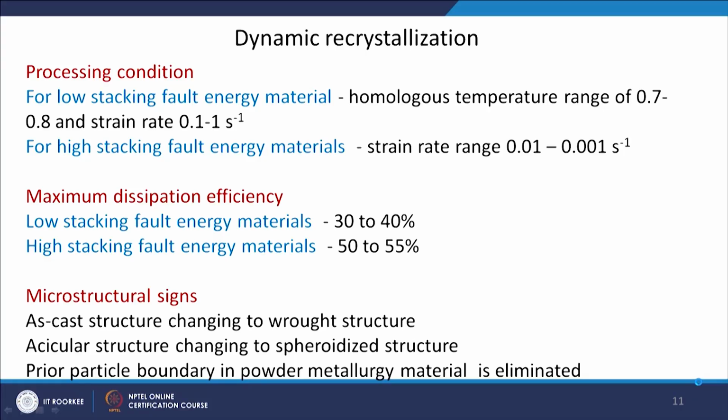So, wherever you have high efficiency, 2-3 samples from there, then maybe a couple of samples from the unstable region to identify whether in these regions some defect is occurring. Okay. So, that will be able to validate your processing map, that it has been generated properly.